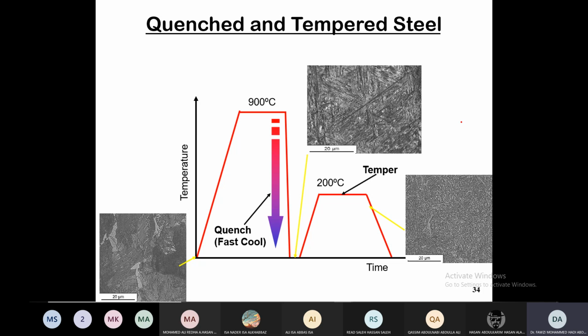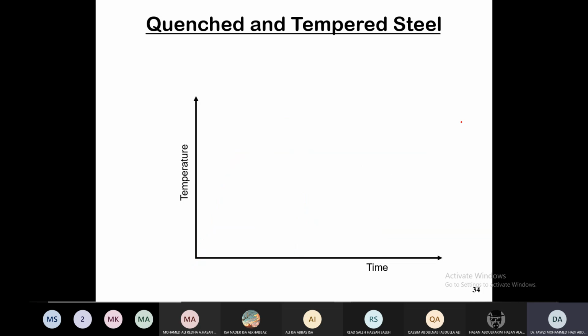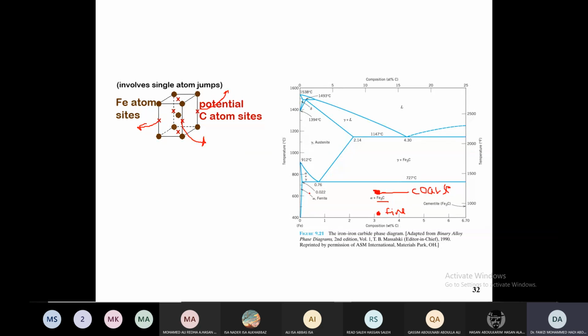When you heat treat, let's go to the phase diagram. Okay. When you are somewhere, anywhere here, if you have martensite, or not only martensite, if you have any phase, if you have pearlite, whatever phase you have, if you raise the temperature and go into the austenite zone, you will get the austenite phase. Clear? Clear.